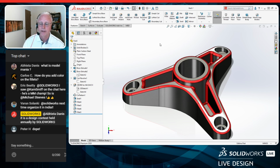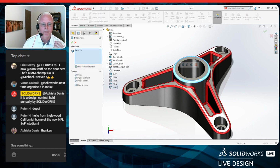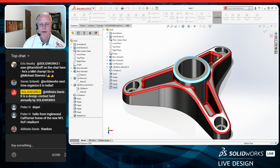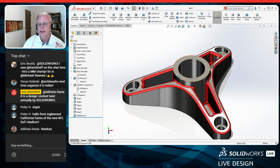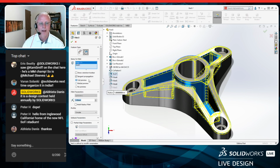A great way to go and just change one fillet or remove one fillet. But the easiest way to do it is to use the delete face command. So I'm just going to choose delete face, and I'm going to make sure delete and patch is turned on. So just delete and patch and hit OK, and that'll delete that. It'll heal those two adjacent faces up to each other. So quick and easy way to get what you want. And the nice thing about it is if this shell ever changed, it's still going to try to fillet that shell.